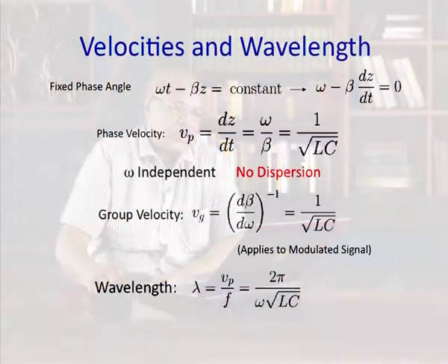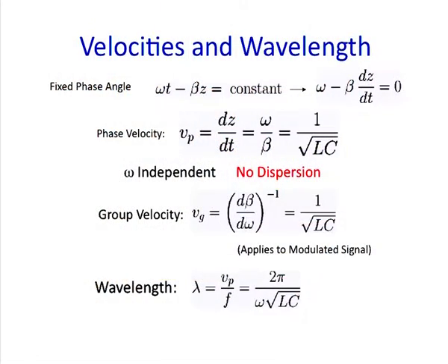The other parameter on the transmission line is the velocity of the signal's propagation. When the wave is propagated, at every point and every instant the phase of the line is different. So, if we put omega t minus beta z equal to constant, then we can find the speed of the signal.